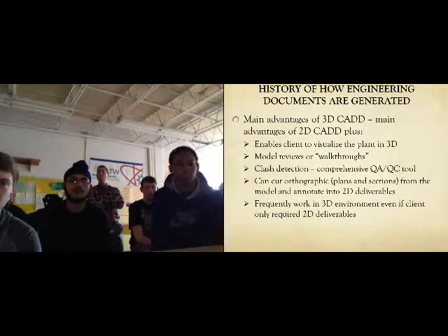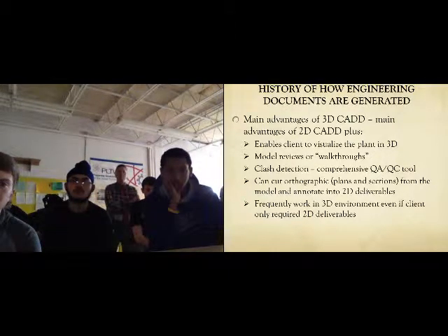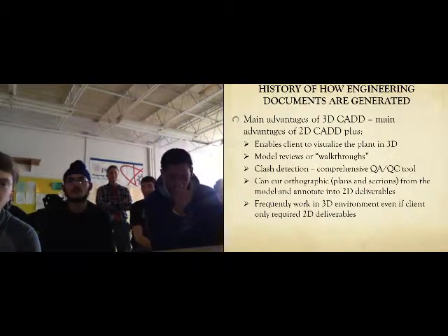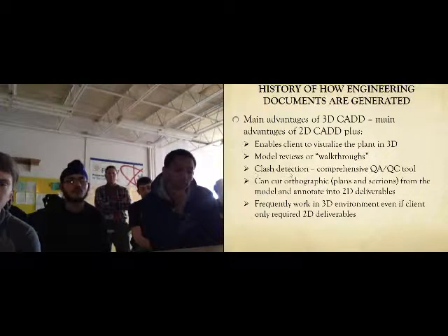That's a safety issue. Let's say there was a problem and you didn't leave the operator enough room and they couldn't get out of a certain area if, say, there was a fire or there was a leak in a chemical system. So a lot of this has to do with safety, which is very big in plant design nowadays, to make sure the operators have the required room that they need to do the work that they need to do. There's also something in 3D CAD called clash detection.